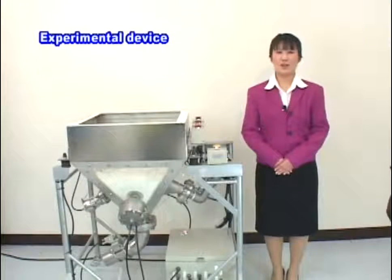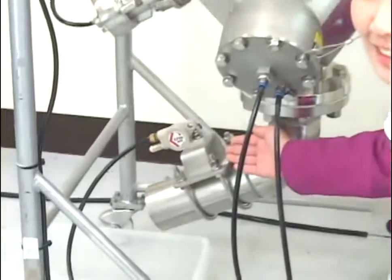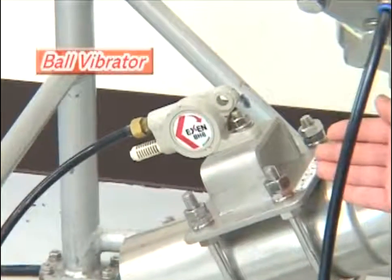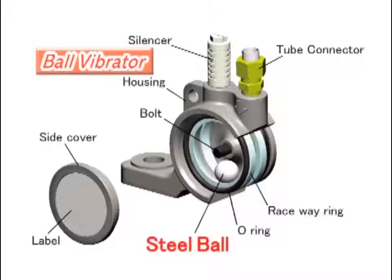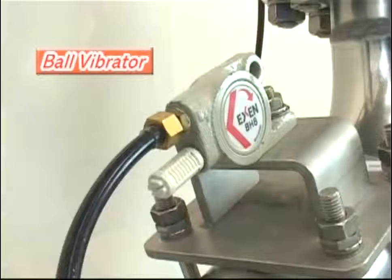EXEN has a variety of devices that can do this. One of them is the ball vibrator. It is useful in tight spaces or places where you need just a little vibration. The ball vibrator uses compressed air to increase rotation speed of steel balls and create vibration through strong centrifugal force.